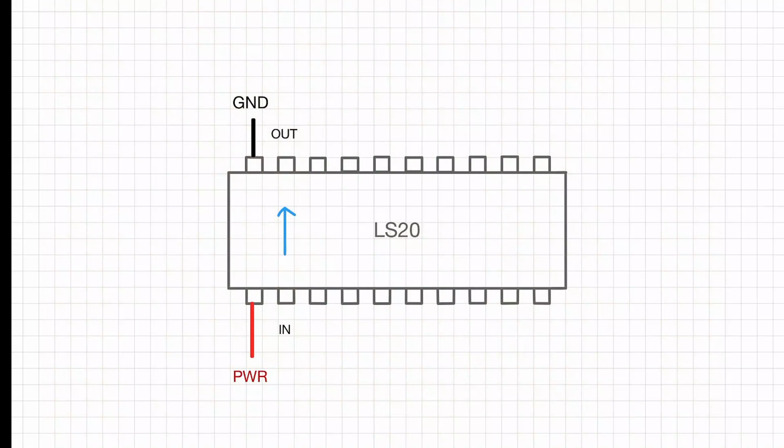The LS10 series IC has a simple wiring diagram. The input pins are directly offset from the outputs. Please note, however, that the power and ground pins do not follow the same convention as one comes to expect with most 74 series ICs. Power comes in on pin 1, and the highest pin number, the pin directly opposite pin 1, is ground. Missing this detail will cause operational issues.